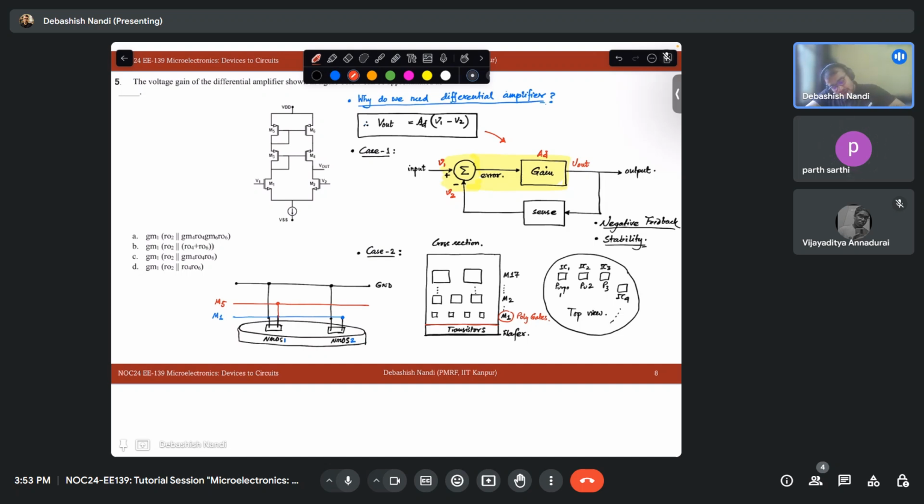Now can you tell me why, in this context, I put the cross section of these metal lines like this? The cross section is very high, and as we go down, the cross section is getting lower. Why does this happen? You should use common sense: the cross section of any wire is directly related to its resistance, right? As your metal layer 17 is far away from the transistor, there will be a series resistance drop because of the length the signal has to travel.